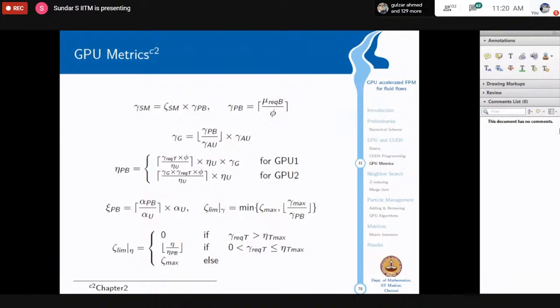How do you know you get speed up in all these classes of problems? Because I am using the same incompressible Navier-Stokes equation, only changing the appropriate boundary condition. I am using Chorin's projection for the entire numerical simulation, and the finite point set method to approximate the spatial derivatives.